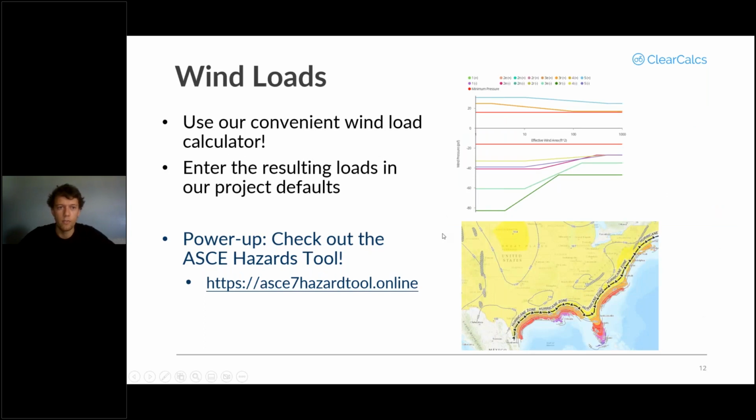The last thing here is for wind loads. We have a very convenient, I think, wind load calculator. You'll see at the end, you get a nice little graph like this showing for the different wind area, what's your wind pressure in PSF. So you can take that and put it in your project defaults, and it's going to make your life a lot easier. And a cool tool here is the ASCE hazards tool.